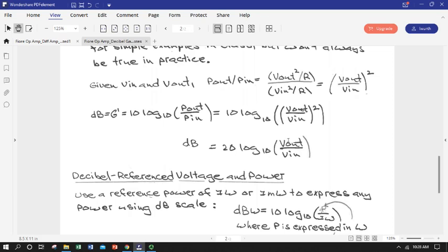So I'm going to express 10 volts in decibels with a 1 volt assumed reference. So I'd put 10 volts in for V out, I'd divide that by 1 volt for V in, so I'd have 20 log base 10 of 10. The volts would cancel, as they need to for the logarithm function to operate on it, and so log base 10 of 10 is 1, since 1 is the number I would raise 10 to in order to get 10. So I'd get 20. That would be a 20 decibel gain equivalent, and that would be considered a dBV, or decibel voltage expression.